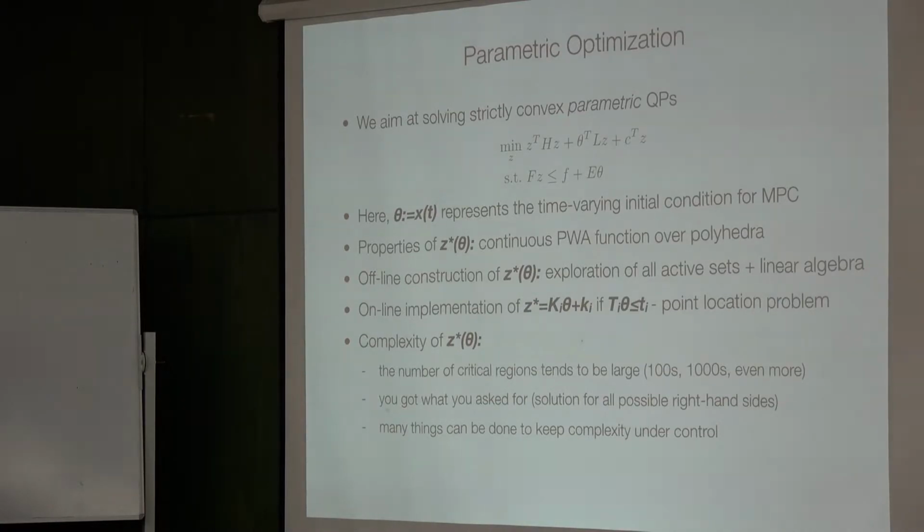With offline optimization, the Hessian and the constraints have to be fixed, set in stone. That means you have zero flexibility in changing your MPC setup on the fly. That's a huge disadvantage of these methods. So if you have enough hardware resources, definitely go the online way.